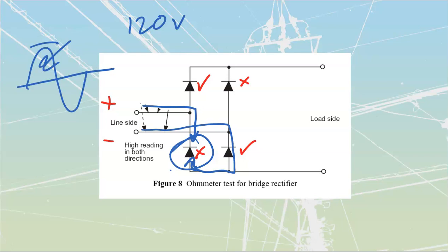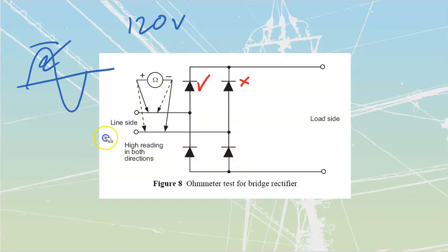There is an ohm meter that is going to be shown over here as well. The ohm meter is to do with testing of these ones. And what we're doing with this testing over here is we're forward biasing, and we're going to be checking to make sure that I don't have any of these diodes that are placed in here incorrectly. If one of these diodes is placed in here incorrectly, we'll start with this one over here.